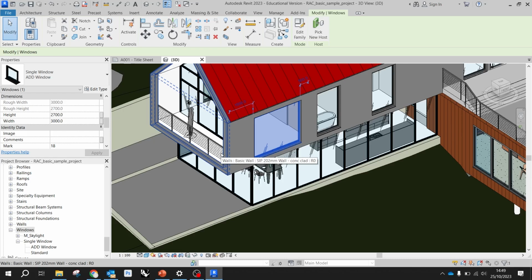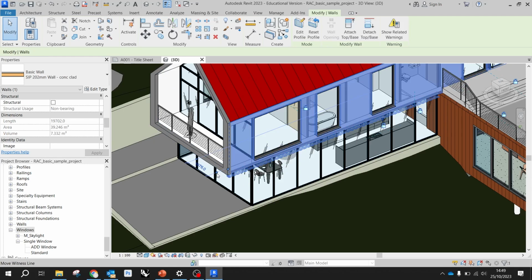While in here, this extrusion, if I pick it, is not just a simple extrusion. It's a wall. So it carries certain information, and one of them is whenever I put a window or a door on it, that wall will be parametrically flexible and accommodate that window, that door. So you see the potential of it.